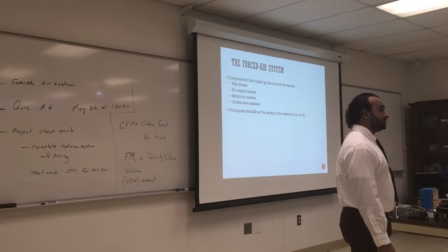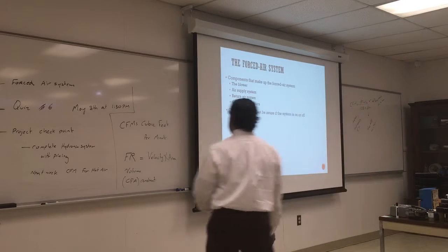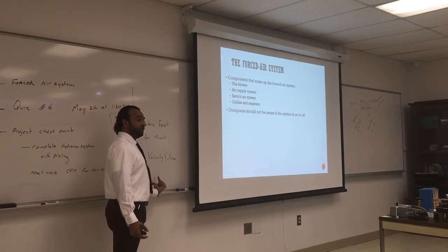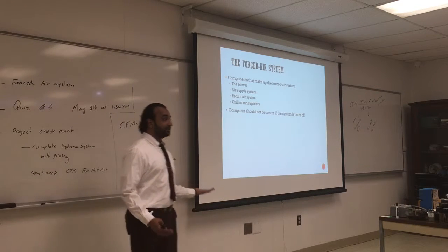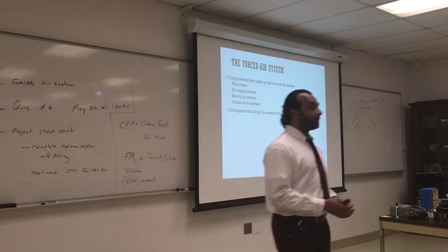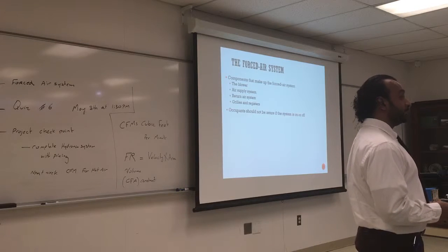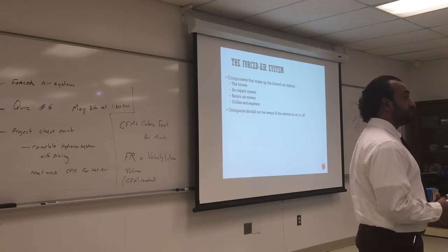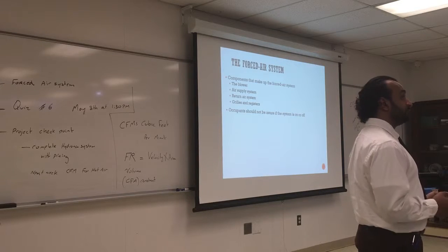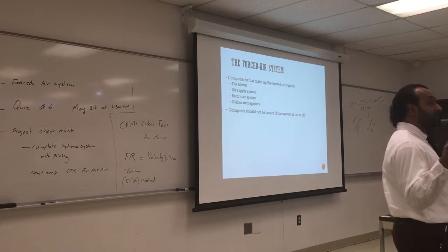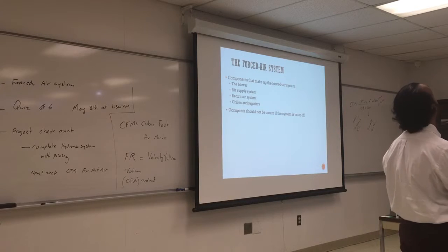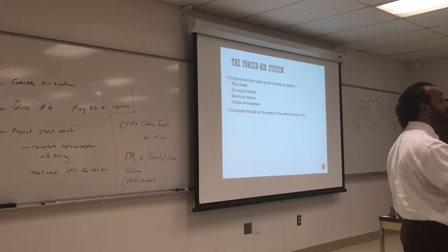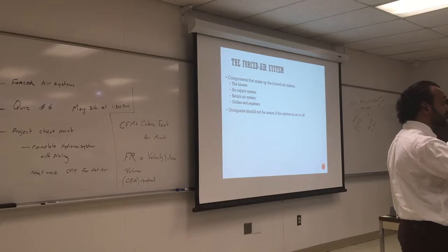The bigger the register, the smaller the velocity. Big area, small velocity. Slower air means quieter, less draft, less flow. Do we always want less flow? Not necessarily, depending on how many of those you have. If I turn off this mini split, probably you cannot hear the air here at all. Why? Because we have 1, 2, 3, 4, 5 registers. So the flow is very slow and it falls quietly.